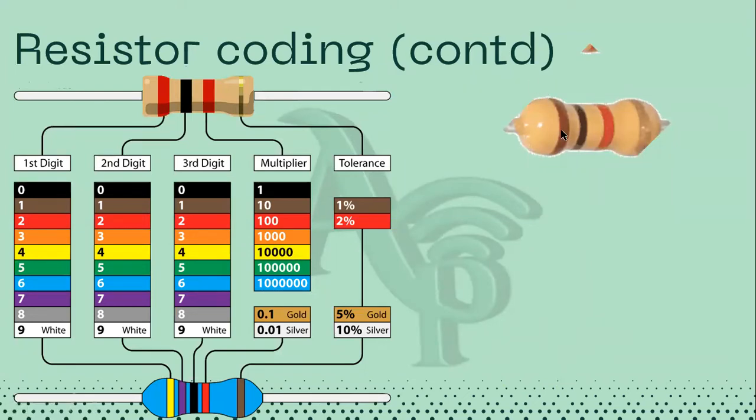All right, so now take note of the resistor. There is a side where the colors are closely packed together. There's always a side in the resistor where the color bands are closely packed together like this. You start counting from that end towards the side where they are loosely packed together. Okay, so we are using this as a case study, as our example.